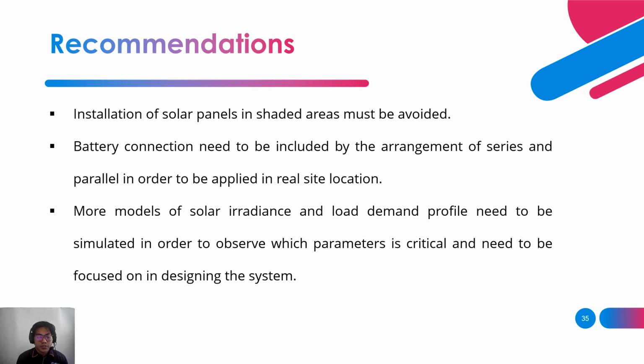For recommendations, installation of solar panels in shaded areas must be avoided. Secondly, the battery connection needs to be included by the arrangement of series and parallel in order to be applied in a real site location. Third, more models of solar irradiance and load demand profile need to be simulated in order to observe which parameters are critical and need to be focused on in designing the system. Last but not least, we can use other controllers to improve the voltage and current performance of the battery and PV panel.